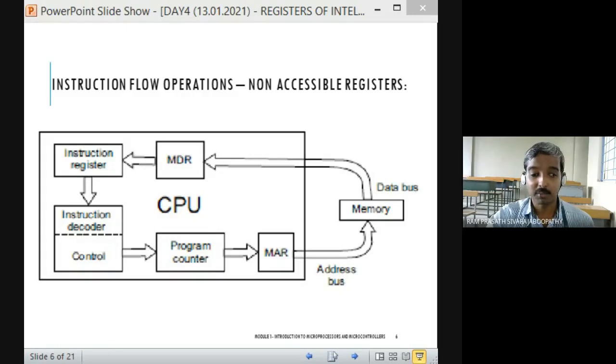In this particular instruction we have 2 bytes. Later I will explain how it is 2 bytes. As of now, for explaining this concept, I am typing. Clear? See, what I wrote above is the instruction, and for what I wrote below, the corresponding code in memory locations, 2 bytes we are going to store: 3E37. Clear? We don't know the meaning of 3E, but the computer, the CPU knows. So 3E stands for, according to the machine, move an immediate data to accumulator register.